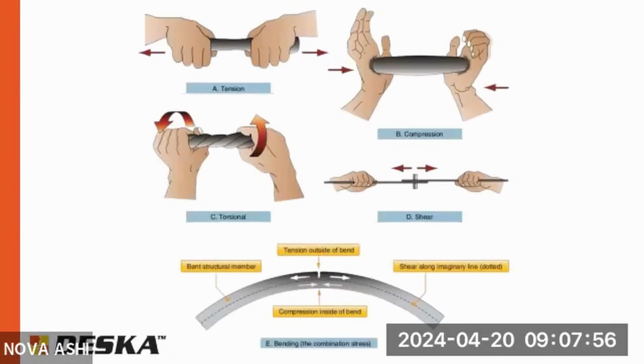Just to give you an example of each. Tensile forces would be an example, would be a rope, right? It's very strong in tension, but it has virtually no other strength to it at all. You're not going to push anything with a rope. Compression, columns are typically the most common member in compression. Torsion, that could be an axle or something. There aren't a whole lot of members in say a residential home that have torsional forces.